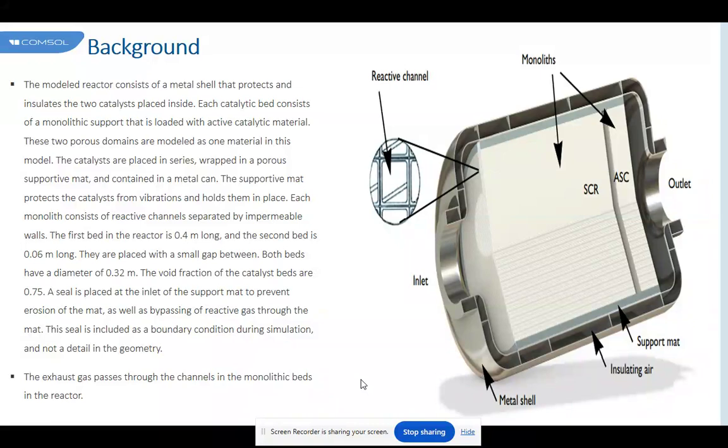Ramanathan and his colleagues in 2004 examined the effects of the solid conduction on the hysteresis locus and showed that the precious platinum group metal, PGM, loading needed to obtain light-off in a metallic monolith is about a factor of 10 smaller compared to a ceramic monolith, with all other parameters fixed.